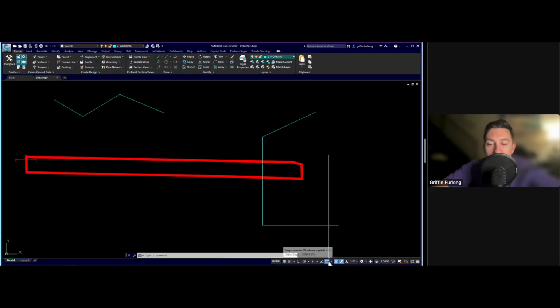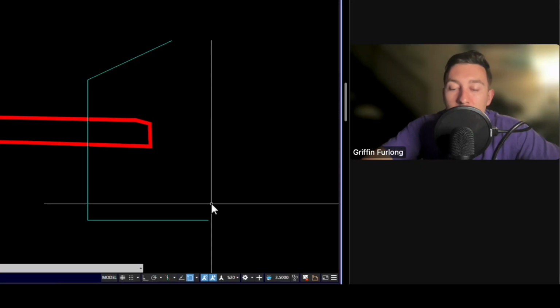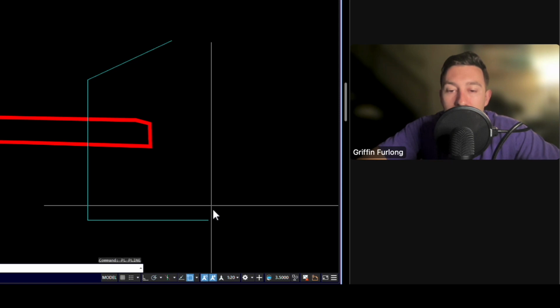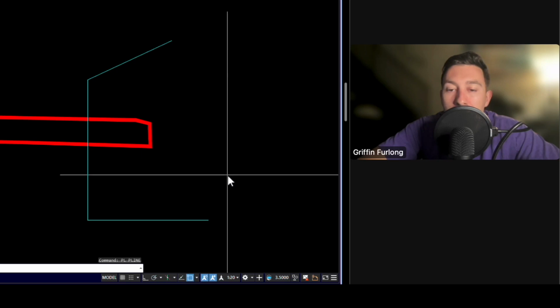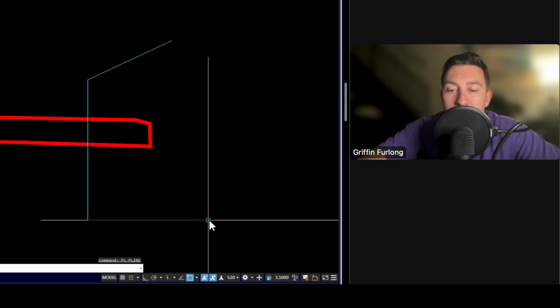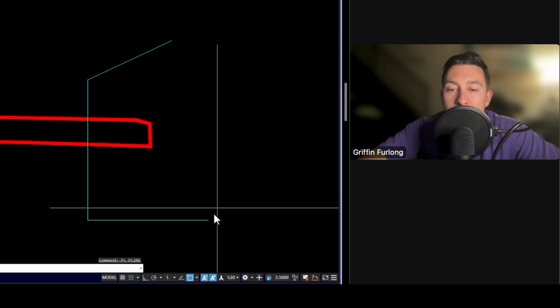And just to keep in mind, we're going through all the F commands. So this one's F3. So if you wanted to toggle snaps, you can toggle by pressing F3. So I'm going to show you what that looks like. I'm going to do the polyline command. Notice how I hover close to an endpoint. It's going to show you that green little box right there. That means that it wants to snap. So as I get closer, it wants to snap to the endpoint.